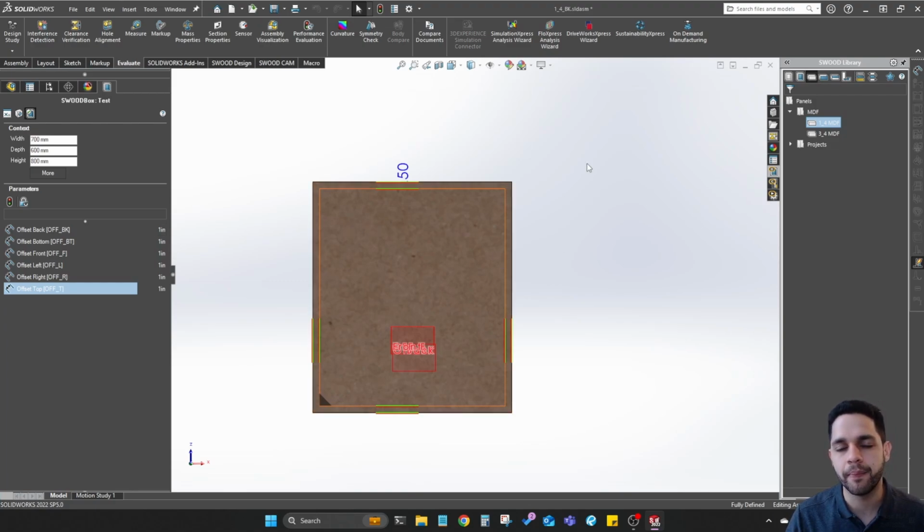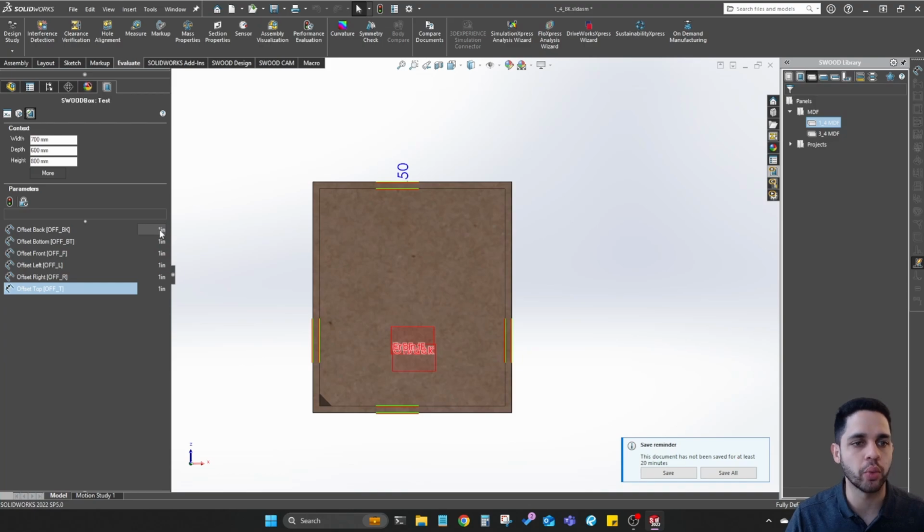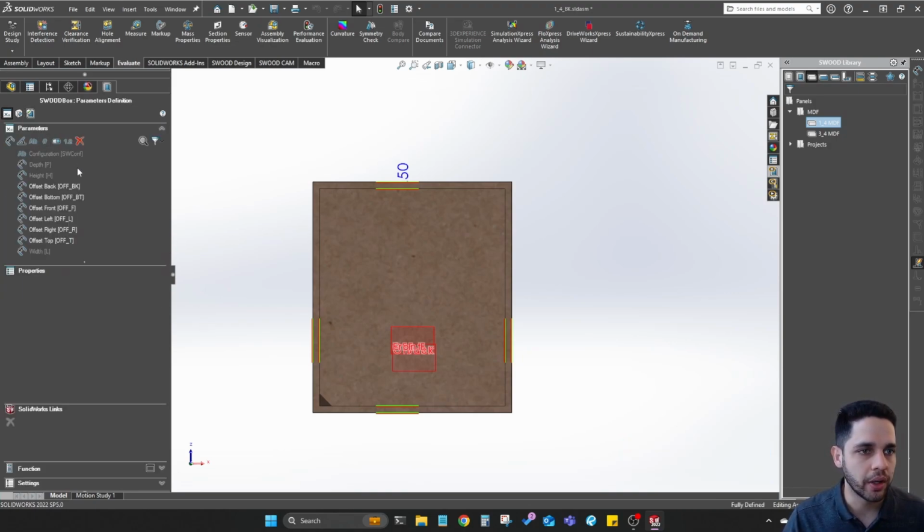So if I wanted to change my dado to 3/8, if I change it in one place, it'll change all these variables at once rather than me having to go in and manually input that 0.375, 0.375, so on, so on, so on. Too slow. So what I will do, I'll jump over to my variables definition,